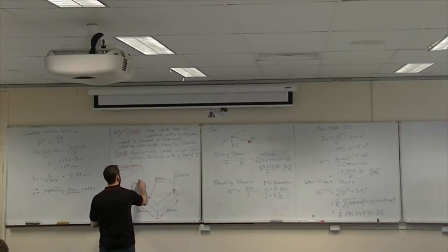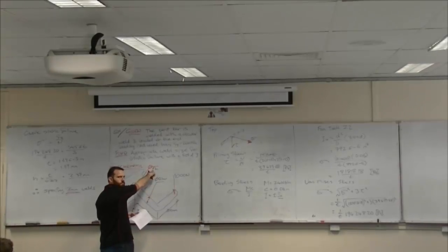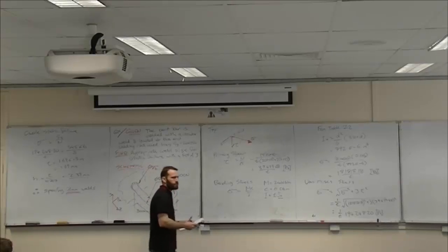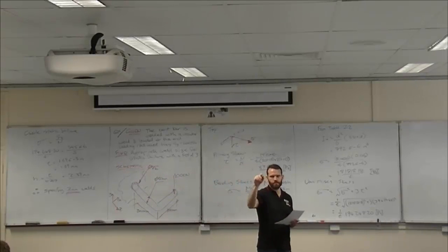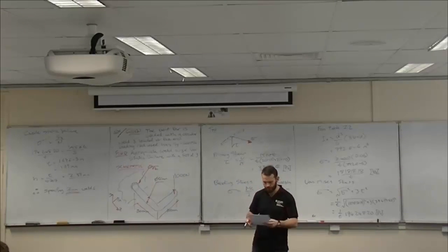And we have a weld here. I'm not entirely sure how to specify a circular weld. Put a circle on the end of the, you know where your arrow turns? Put a circle around that, for all around. All around. Okay, cool. Do I leave that triangle there? Yeah, cool. And same with the other one, that last question you had, instead of putting 2 in there, you put the 1. You do a circle and it says all the way around. There you go, perfect.